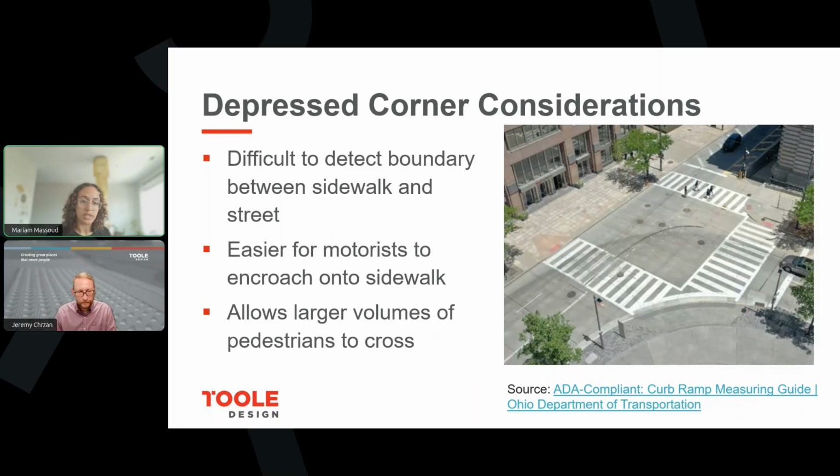Kind of related to the flatter grades, it means that it's easier for people driving to encroach onto the sidewalk while they're making turns. And then another challenge is that a driver who sees a pedestrian entering or using a blended transition or a depressed corner might not always know which crosswalk the pedestrian is going to. So it can add a little element of confusion or unclarity.